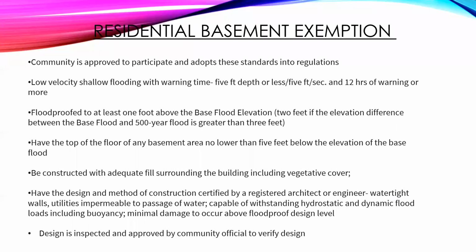And so I wanted to spend a little bit of time talking about residential basements for about the last 10 minutes or so. And so this is a special program with FEMA. So you, again, have to apply to this program and be approved to be able to adopt these regulations and then permit compliant residential basements. And so it has to be in a place with low velocity and shallow flooding that is 5 feet of depth or less, 5 feet per second or less, and then 12 hours of flood warning time or more.